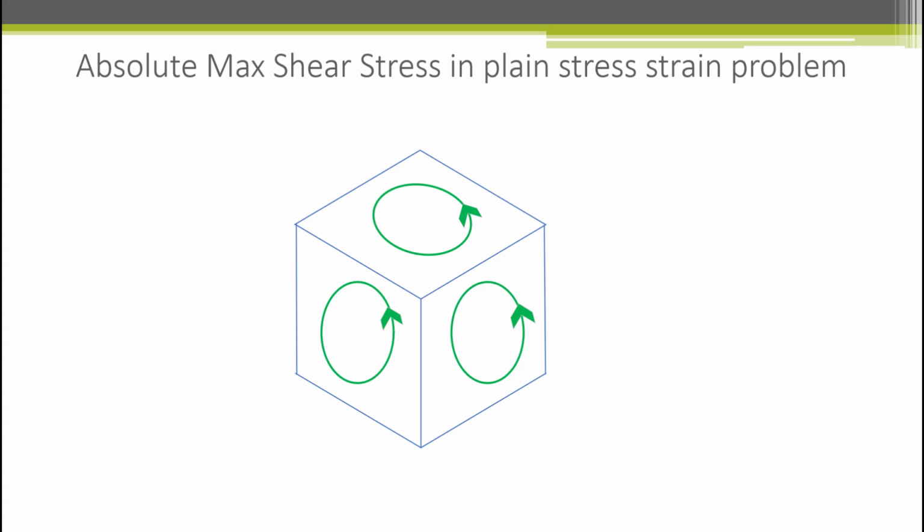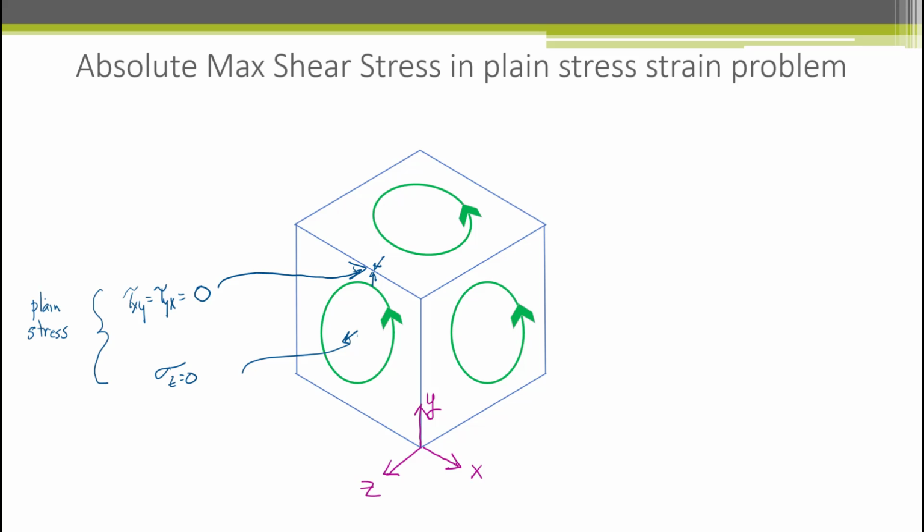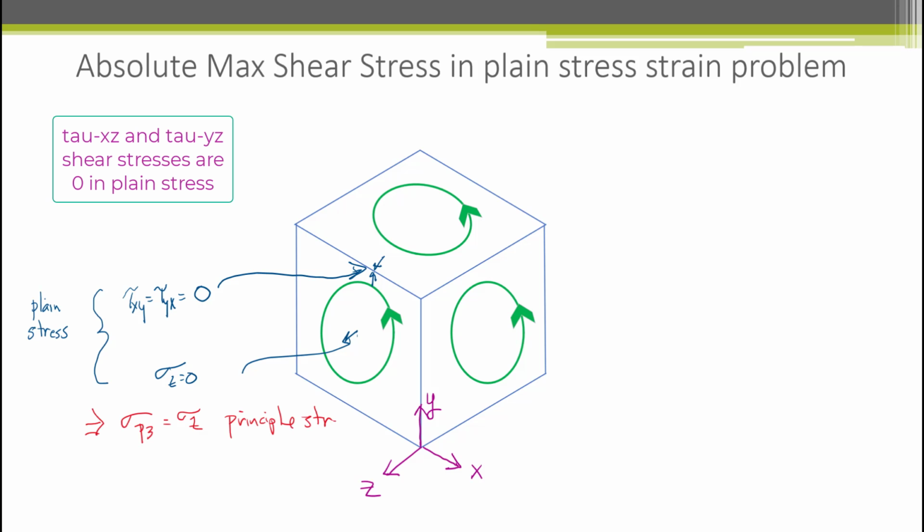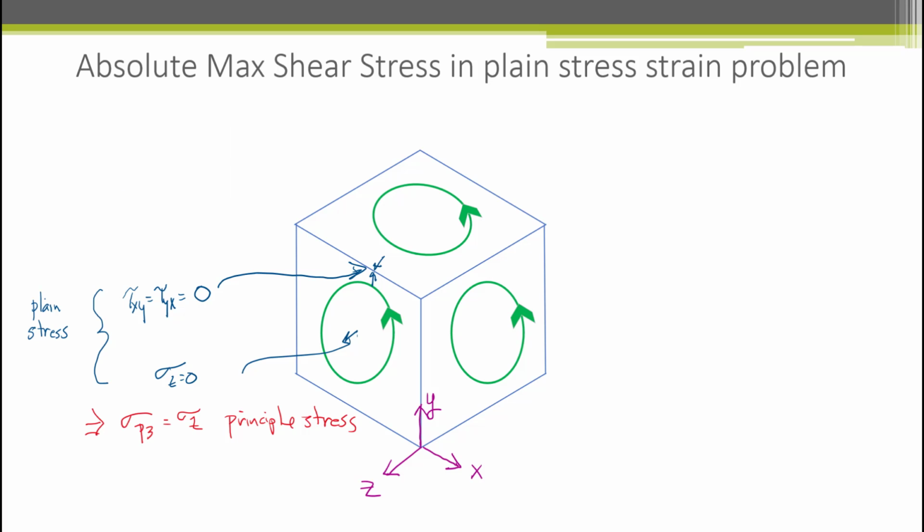This graphic shows what I mean by rotating the stress element about the other 2 axes. Let's first make sure we understand the coordinate system, which is now shown by the x, y, and z axes. Even though we represent the plane stress element as a square, it's really still a cube. But the z direction principal stress is 0, and the xz and yz shear stresses are also 0. There is some orientation for the stress element where there are no shearing stresses on any of the faces.